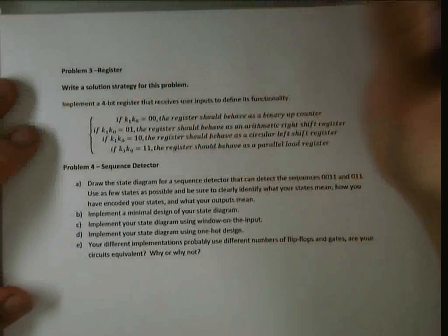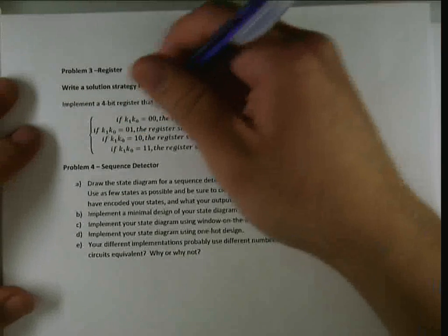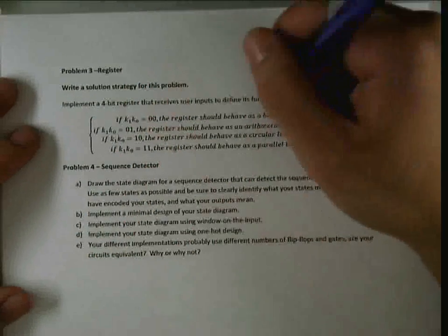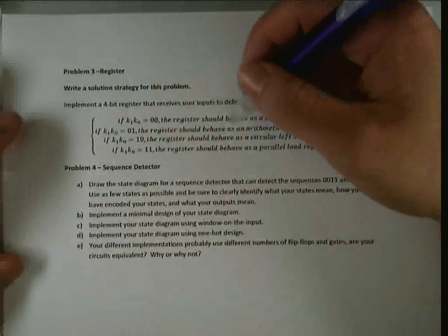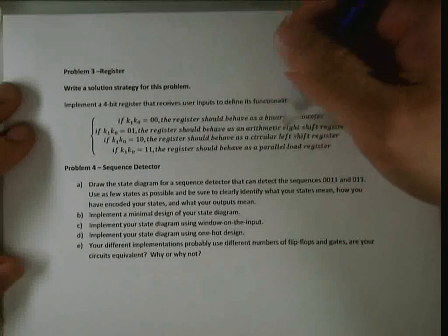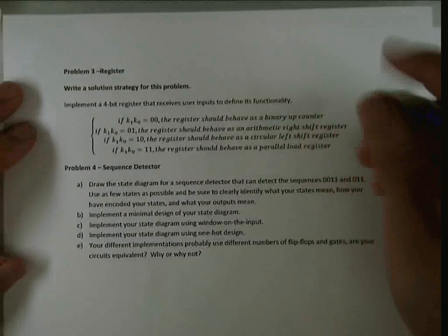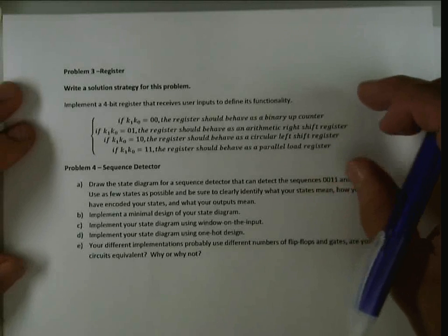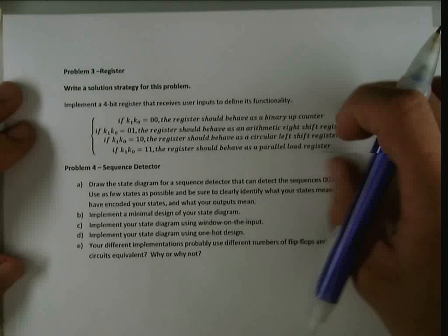So if we're picking between different inputs, then we just want a multiplexer. Since I have 2 bits that I'm using to select, I'm going to have a 4-to-1 mux in front of each flip-flop. The next important thing is, since I'm designing a register that does shifts primarily and parallel loads, these 3 functionalities are much easier to do with a D flip-flop. Well, sorry, that's not correct. I will make my register out of D flip-flops and use the logic here.